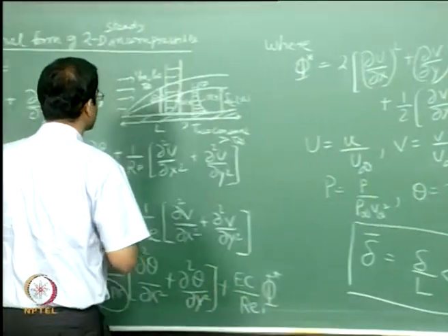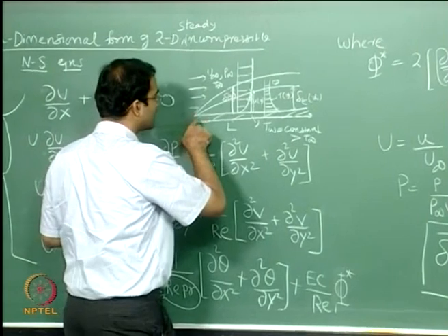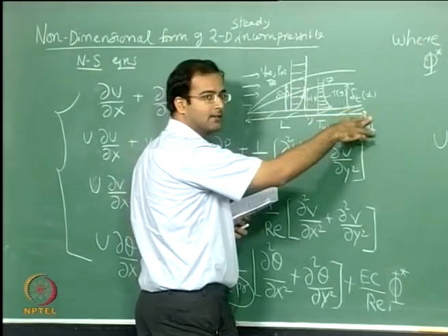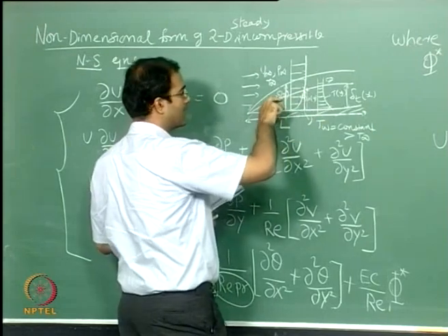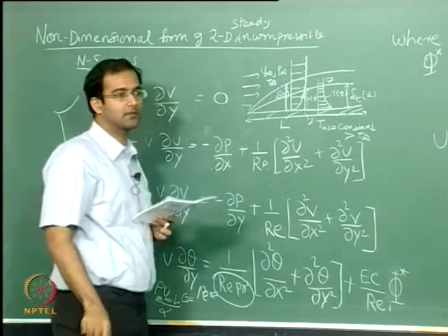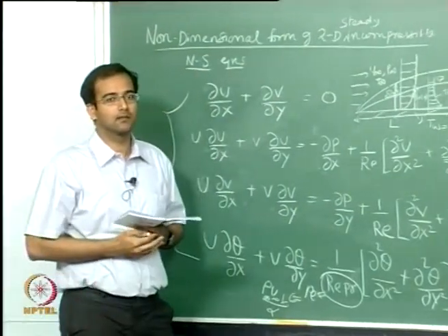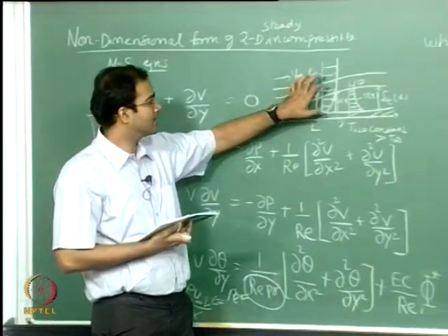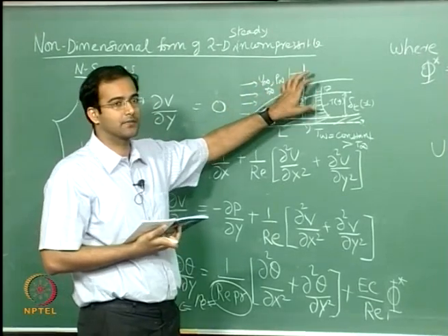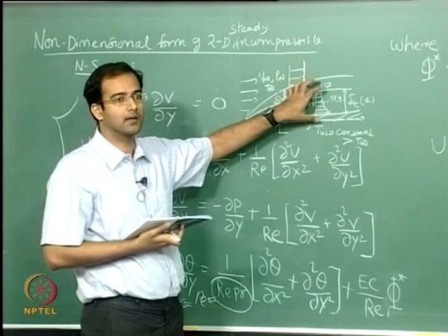In the boundary layer, I am looking at x which is varying from 0 all the way to the length L, and as far as the y coordinate is concerned, I am mostly concerned within the confines of the boundary layer. The assumption here is that the boundary layer is the region of interest because the viscous effects are very important here.